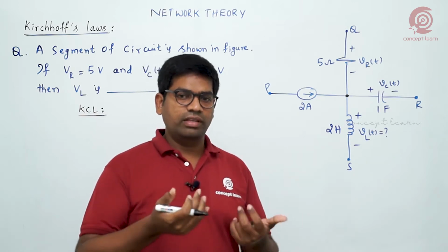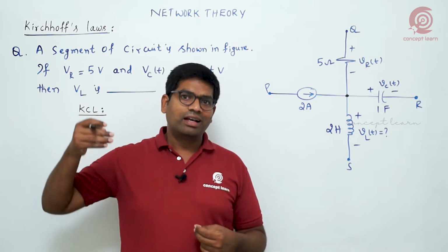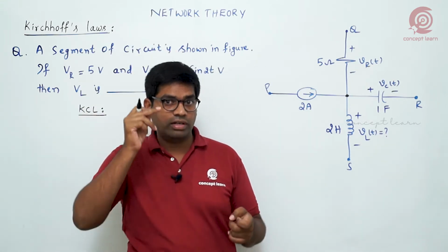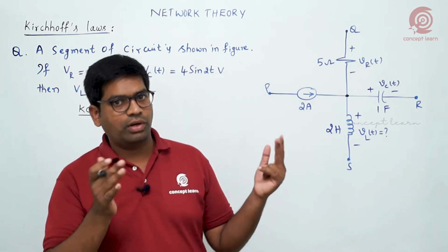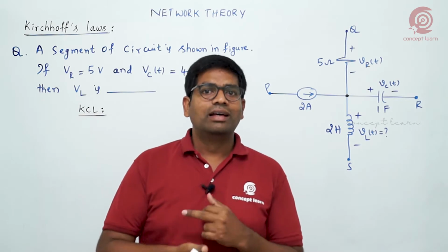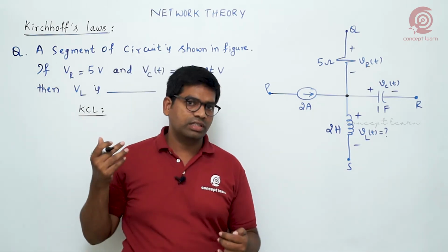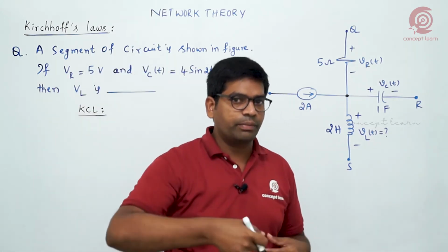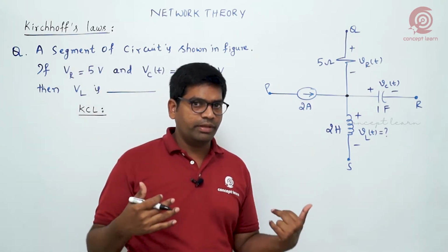Means these are taking energy. So when power is absorbed by the element, current will be entering into the high potential, which we already discussed when we differentiated active as well as passive elements. Active means current is coming out of the high potential, that is delivering power. When current is entering into the high potential, it is absorbing the power. So passive means definitely absorbing.